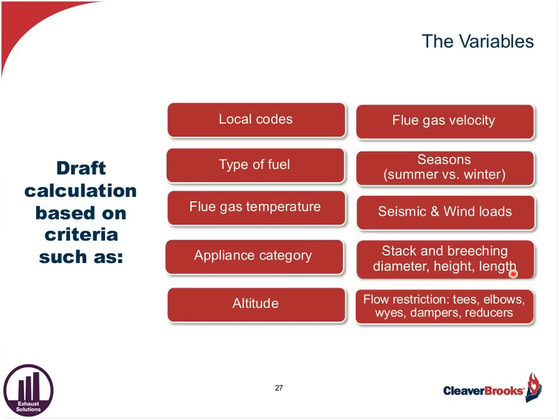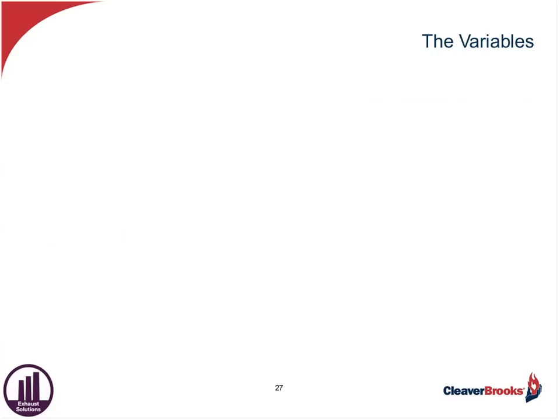And then when I'm doing that and laying it out, I have to think about other things like, where are the flow restrictions? Do I have T's and elbows? What about Y's and dampers and reducers? These will all affect the resistance to flow and increase the pressure drop.